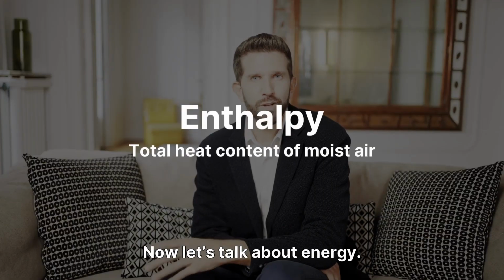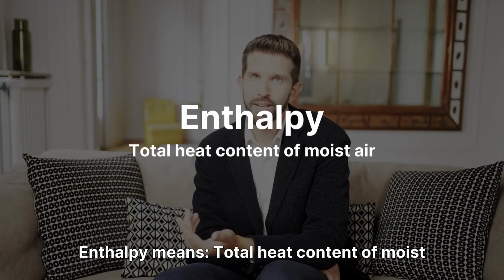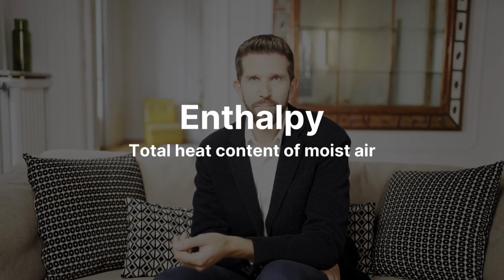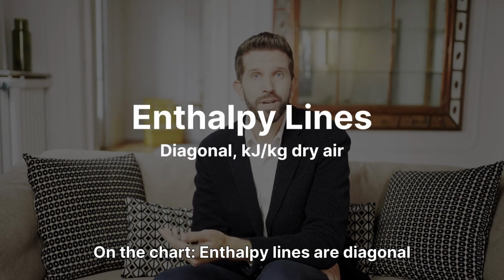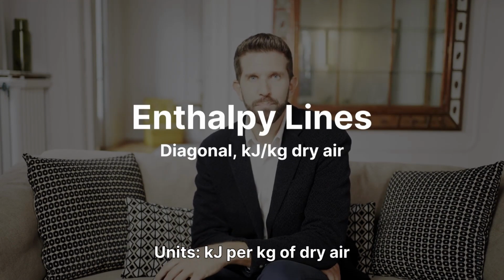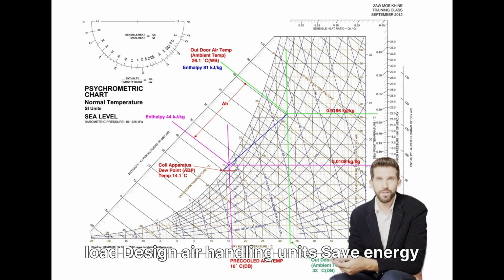Now let's talk about energy. Enthalpy means the total heat content of moist air. It includes sensible heat and latent heat. On the chart, enthalpy lines are diagonal, with units of kJ per kg of dry air. HVAC engineers use enthalpy to calculate cooling load, design air handling units, and save energy.